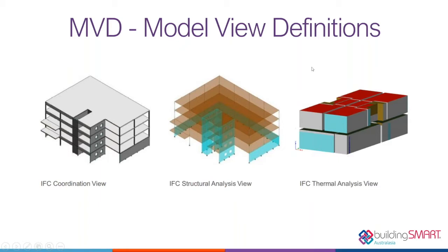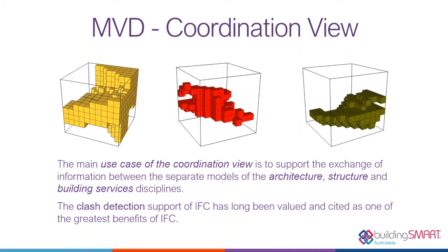There are many other model view definitions, such as operations and maintenance, and some new model view definitions introduced in IFC 4 that I'll talk about in a second. What a model view definition is really selecting is the information essential for that exchange. Some of these are official model view definitions maintained and developed by buildingSMART, and I think we'll see model view definitions published by various big clients for the exchanges they'd like to use IFC for in the near future.